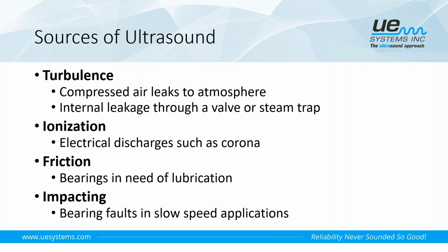So as grease enters the bearing housing, there's less friction, therefore less noise. On the other hand, if we start to apply too much grease, then we'll start to see the decibel level going up. So if we're ever applying grease to a bearing and the decibel level starts to increase, we need to stop because we've reached the threshold where we've started to over lubricate or apply more grease than what's needed.